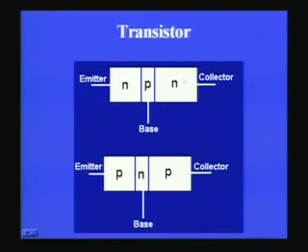You can immediately recall a very similar situation with reference to vacuum tube triodes. These transistors are solid state devices which are replacing the well known olden days vacuum tube triodes. In the vacuum tube triodes, as the name itself suggests, there are 3 electrodes, triode, and the 3 electrodes are called the filament or cathode, a control grid, and a plate.